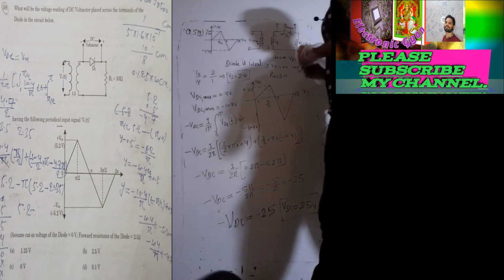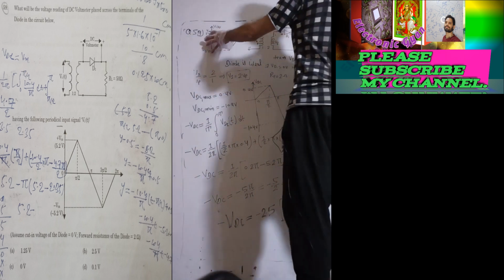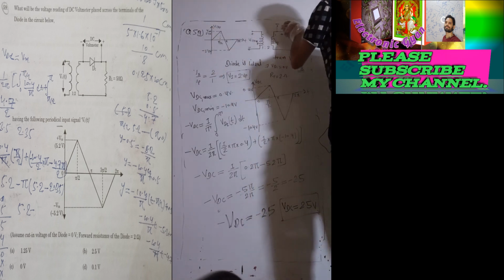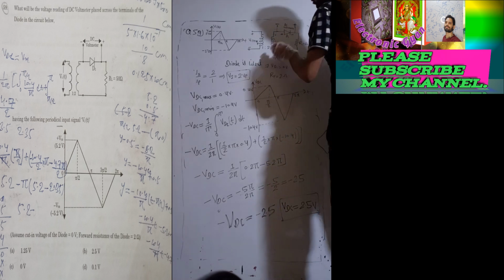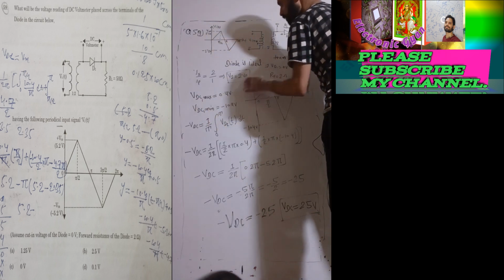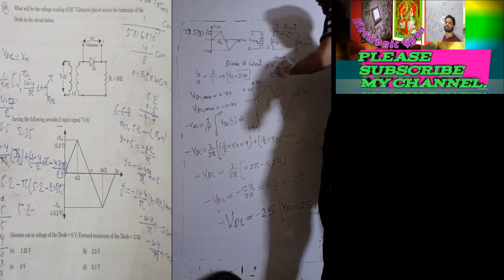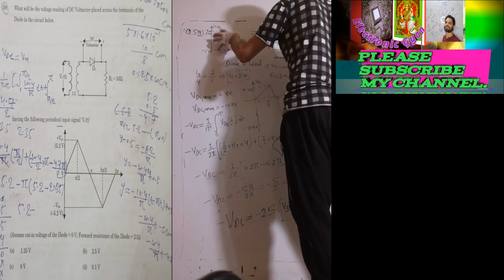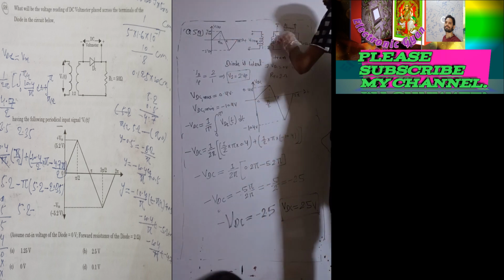What have we done? Just first we considered the positive cycle. During the positive cycle, the diode is on. That time the diode has a forward resistance of 2 ohm. After that we applied the voltage distribution rule, and we got VDC1 maximum 0.4 volt during the positive cycle. Then we saw that during the negative cycle of the input voltage, this diode will be off.